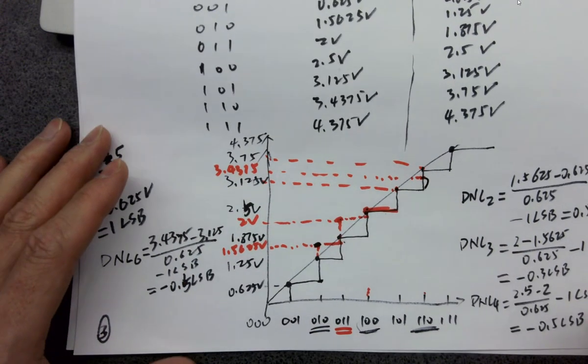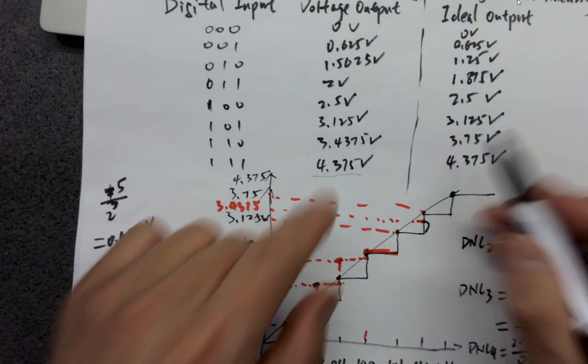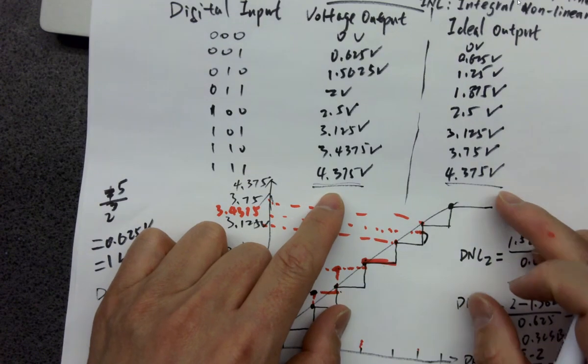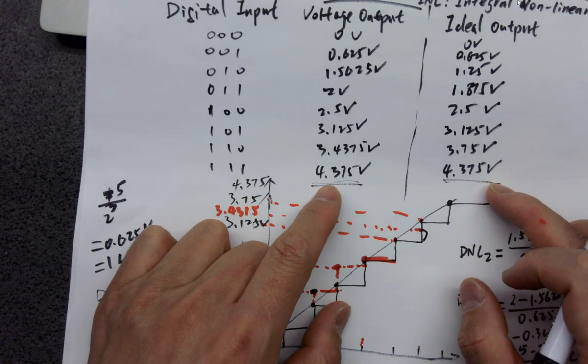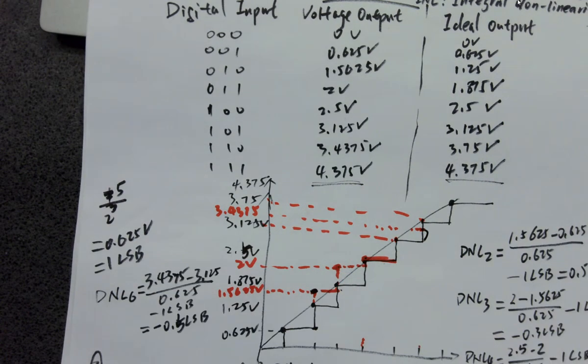And the last one looks like the actual output is fine. However, we are looking at the difference, right? Even though it comes back to the ideal point, the transition has a very weird step size. So which means the DAC has a nonlinearity.